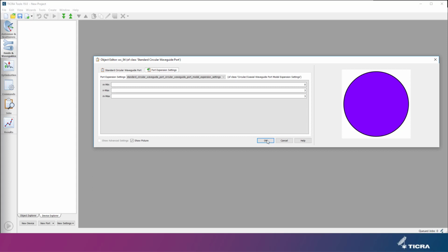Manual convergence test is necessary. That is, after the scattering parameters are calculated, Mmax and Nmax should be increased, and it should be checked if the scattering parameters of interest will change.